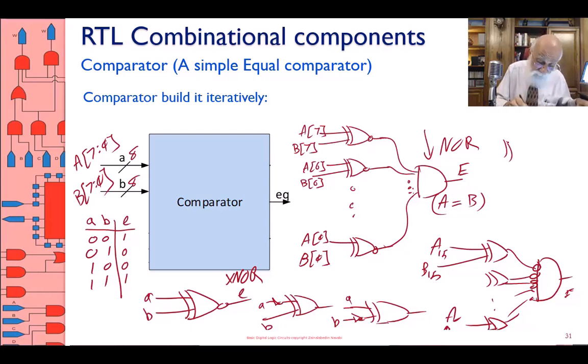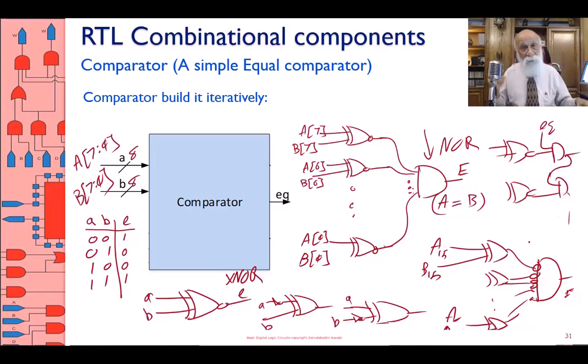So what I'm really doing is XNOR and equal, XNOR and equal. And then eventually the last one will give me the equal output. Maybe along the way two of the bits are not equal. Let's say, for example, A4 and B4 are not equal, and that creates a 0. But then 0 into the AND gate just zeros everything. So at the end, I see no equal.